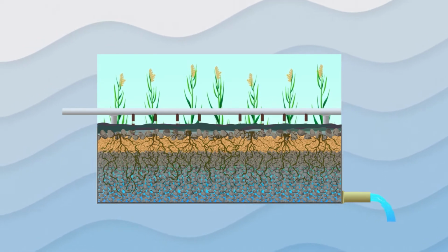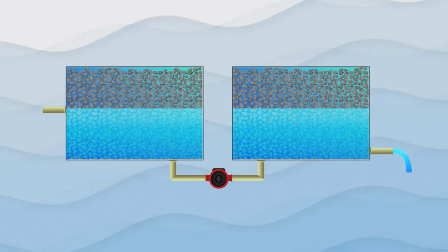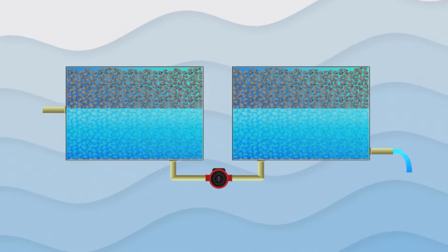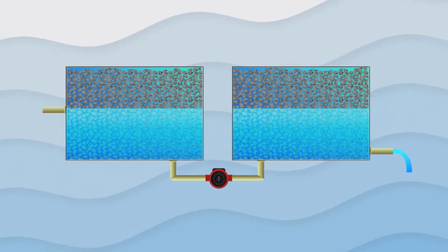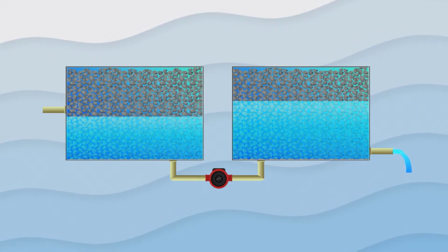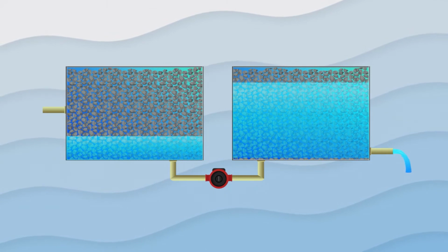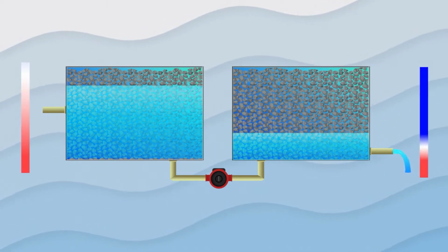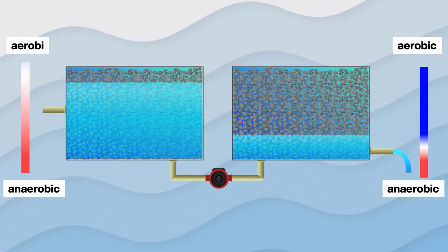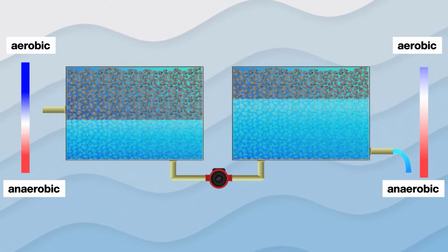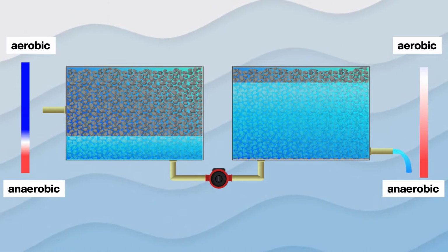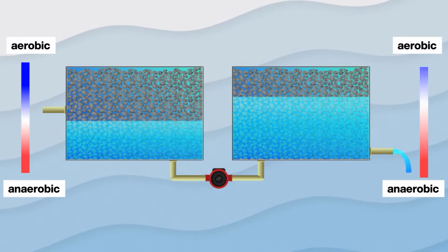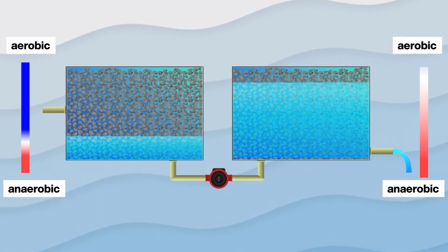Betsy, I have another question for you. Why do some modifications of vertical subsurface flow constructed wetlands use the technology of reciprocating water level change? The reciprocating motion of water creates alternating aerobic and anaerobic conditions in the constructed wetland. This creates a higher biodiversity of microorganisms, which allows the wetland to treat wastewater more efficiently and in a smaller volume per inhabitant.